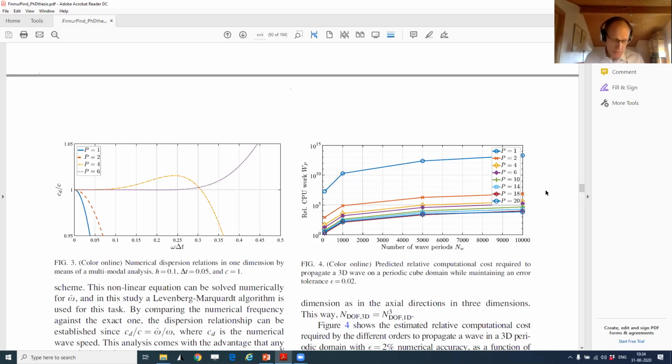And that is certainly true, but there's absolutely nothing that stops us from using a frequency domain calculation method and reaching exactly the same impulse response and transient time signal result. If we have a linear time invariant system, we can choose one or the other path. So I think that those arguments are not necessarily telling why it's advantageous to use the time domain method.